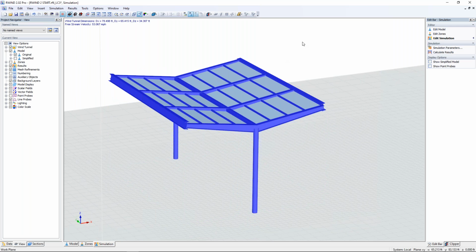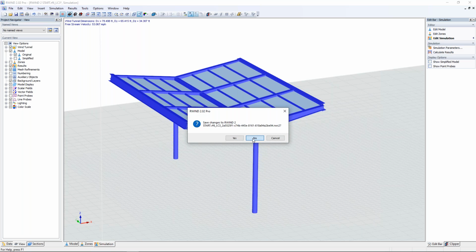But in reality, if we'd really like to apply the wind loads to the roof panels only, and then to have them distributed to the members, again, the program only knows what it knows. So all members were modeled, these surfaces were modeled, everything's brought in based on the center lines, and the wind analysis will be applied to all objects. So what I'm going to do once again is to exit out of our wind.